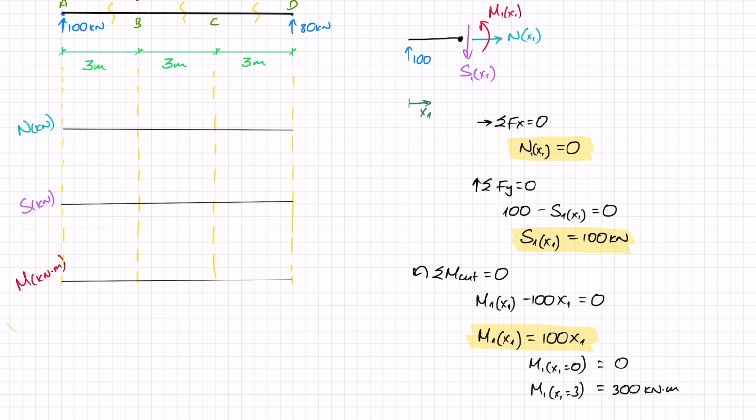So let's discuss what that means in terms of what I need to draw. I'm going to draw out my little cutoff of the beam. I assumed that my bending moment was in this direction. That was my assumption. It came out positive, so indeed it is in this direction. And what I can see is that this direction of moment pulls the bottom bit of the beam and pushes the top bit of the beam. I can see this, for example, as a coupled force. This arrow pulls the bottom and pushes the top.